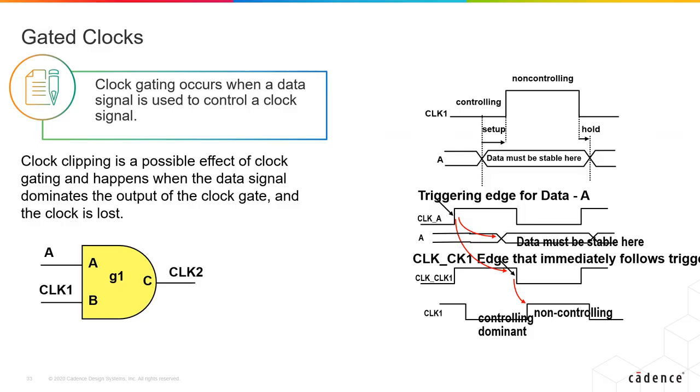Gated clocks are quite common and can help reduce dynamic power dissipation when you have a lot of flops. Just like all other signals, clocks also have rise and fall times, and dynamic power for your design. The fan-out of the clock is much greater than those of most other signals. The data signal, which is the A signal in this example, propagates through these cells.